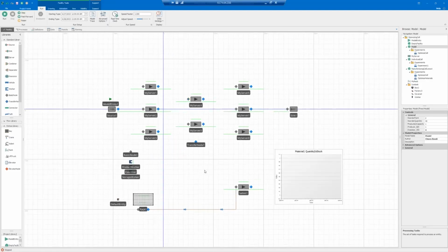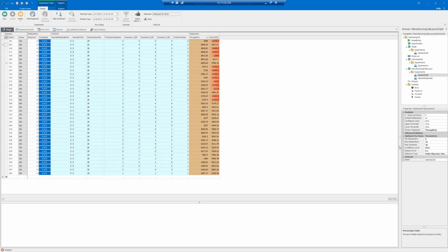Thank you. And now several OptQuest questions here in a row. Can you control how long OptQuest runs for, or does it know when to stop creating scenarios? Yes, so I'm going to go right here, and in our OptQuest parameters, you can specify the minimum number of replications and the maximum number of replications and the maximum number of scenarios that you want to look at.